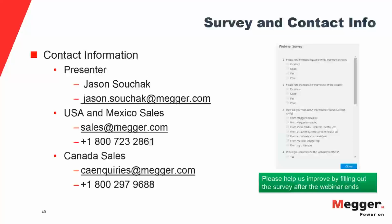Just one more word. Keep in mind what Jason spoke about, what you also saw in the test results, and what experience from Europe since the early 2000s tells us: the defects you are after with PD diagnostics are generally in the hundreds of picocoulombs.